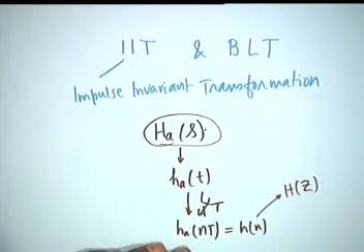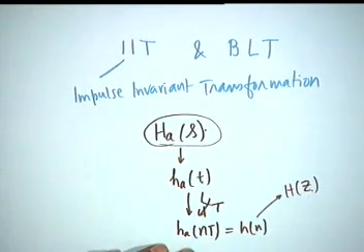No transfer function can stop abruptly at a particular point, because it would disobey the fundamental Paley-Wiener criterion. It would be non-causal also, that is, unrealizable. So no transfer function is band limited, which means that some amount of aliasing distortion is bound to occur. So long as you contain this within tolerable limits, it is perfectly all right.